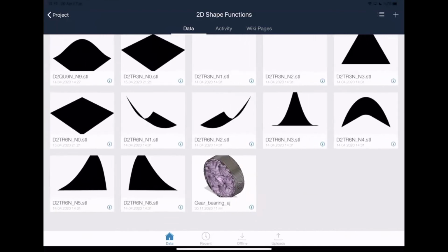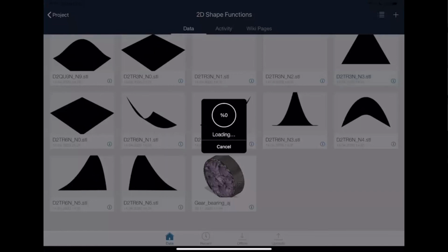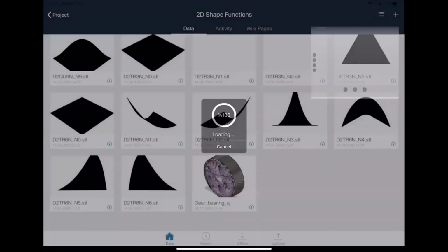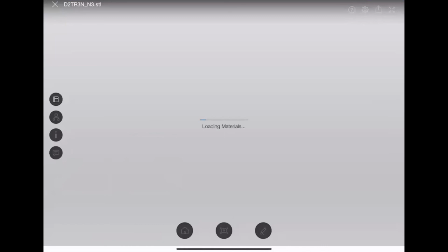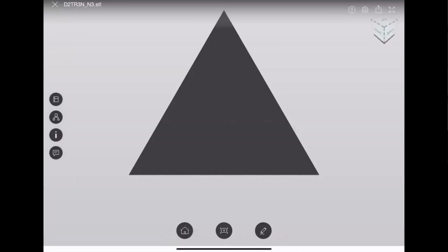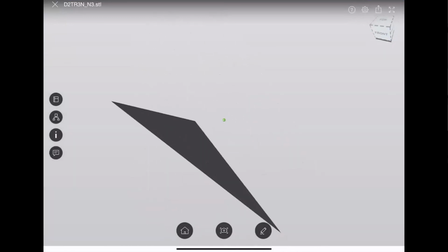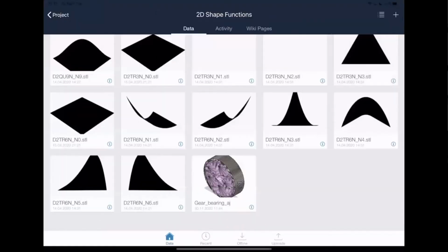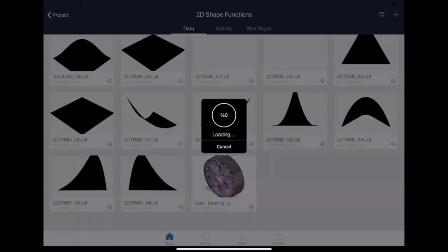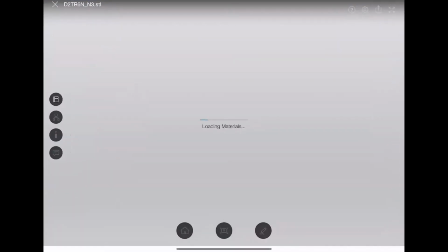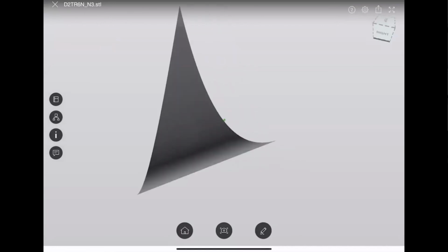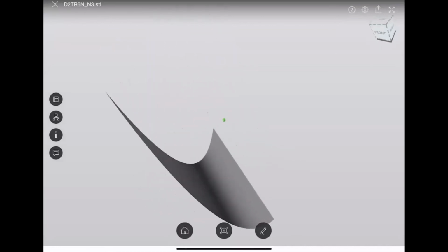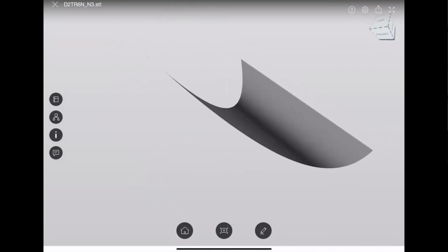If you had quadratic elements, it would be the same game. So for instance, if you had a linear triangle, you would have, again, one corner that is 1 and the other two are 0. So this is pretty straightforward. This is kind of boring. But then if you look at the same shape function, so N3 for a quadratic triangle, now it looks slightly more interesting because it does this nice thing.